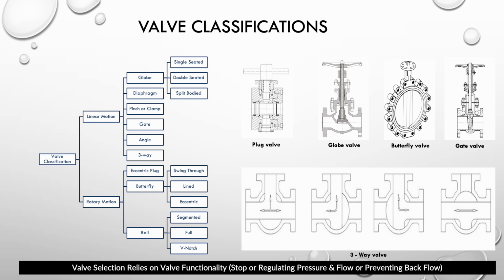The ball valve is doing the same work as a globe valve, but it has way more tight sealing. Ball valves sit between a gate valve and a globe valve in terms of being an on and off kind of thing, and at the same time can be used as control. The reason is that the ball valve has a curvature to it that the gate valve is lacking.